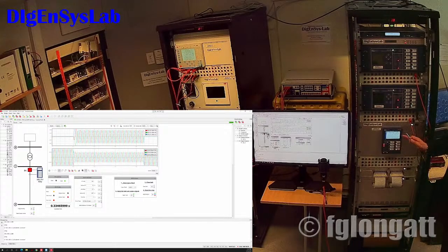I mean, this is the real thing. If you are in a substation and this happened, probably you will be scared because you have so many customers without electricity. Because the fault happened, we open the circuit breaker, okay? Right now, we are totally sure that the relay is properly operating and is clearing the fault, okay?